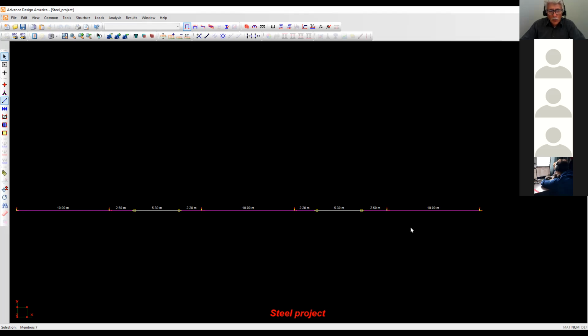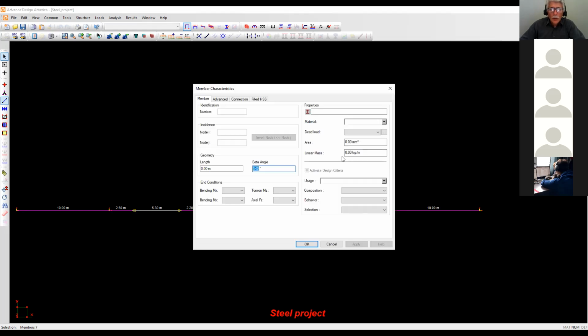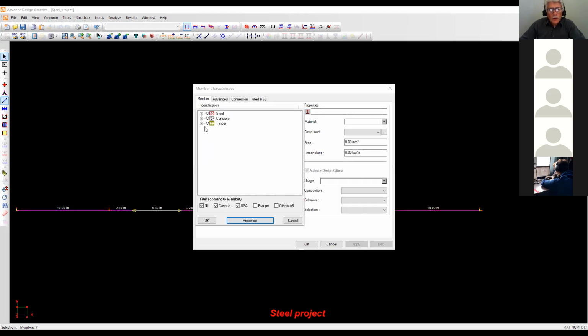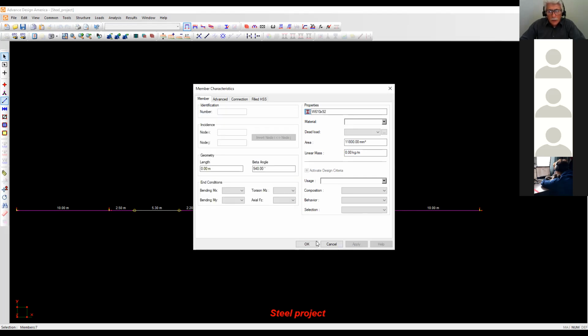100% agreed. Great, okay. So now what I do is I right click, I go to properties, and I come here, and I go to steel. I go to my Y flange, and I go for a W610. So here's my 610s, and I go down to, I replace the 125 by 982. Fair enough. Press OK. And of course, I don't care about the material.